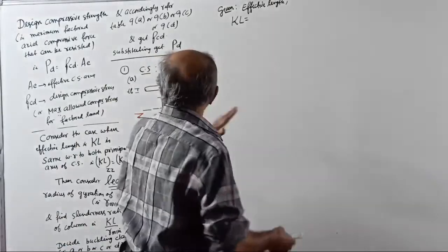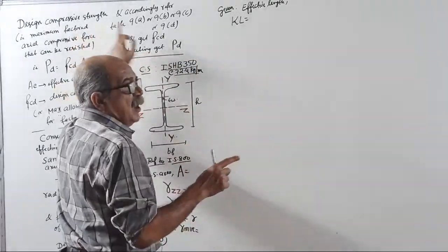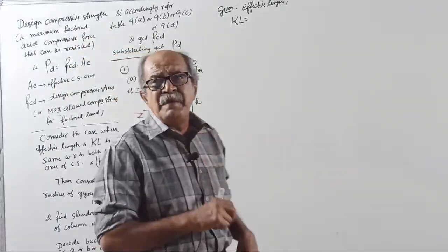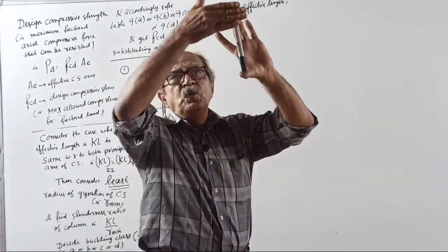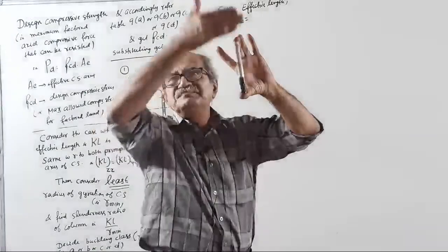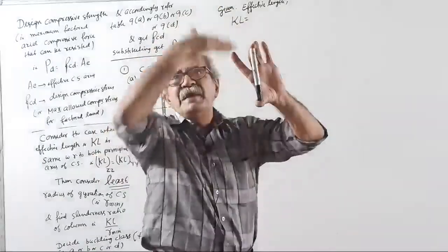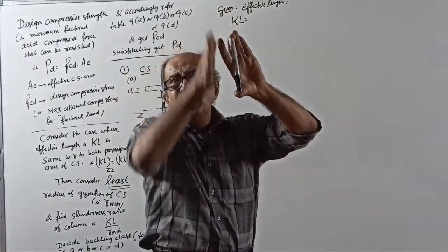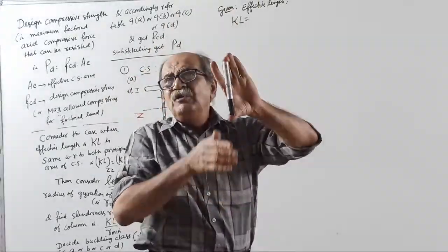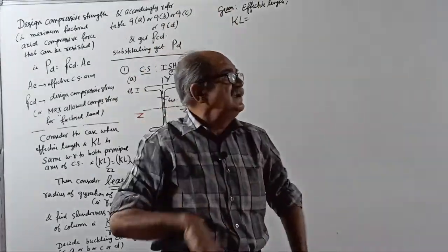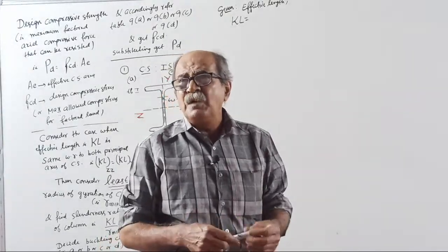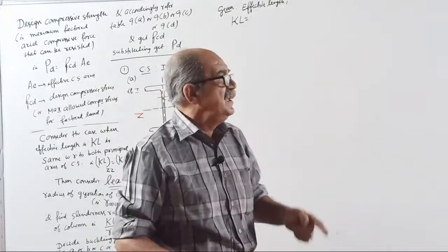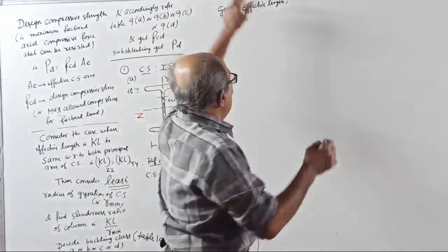So, I have written a brief statement here on how to calculate. And one more important thing, remember: when you consider effective length, one effective length will be this way, about this axis. One more effective length will come here, about this axis. But usually for columns, effective lengths are the same with respect to both axes. If not the same, remember what you have to do?